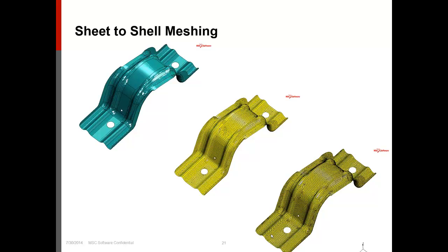One is, of course, considering the curvature control in the geometry. And the second thing to recognize is this can be done with either lower order elements or higher order elements. And when you use the higher order elements, it will put the mid-side nodes on the geometry. The other thing to recognize is you could generate a lower order element mesh and then do a change class, going from lower order to higher order. But in fact, doing it directly as a higher order element is the more accurate thing to do, especially when you have regions of concave type surfaces.